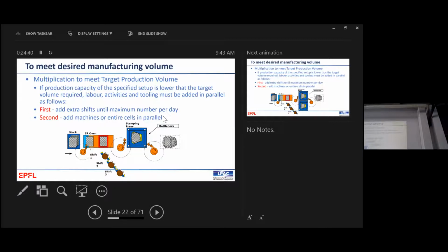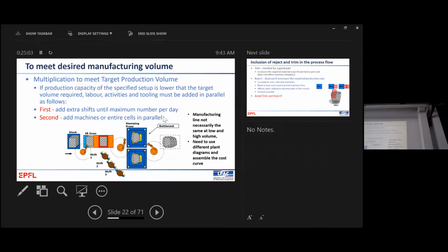One of the issues with composites is their cycle times are longer than metal. The steel video, they're popping out parts every couple of seconds, non-stop, boom, boom, boom, boom. Okay, it hypnotizes you. Composites, it takes a minute to make this seat. So you might need to buy a second machine, which means more CapEx. You have to invest in a second press, okay? And the cost model can include this.